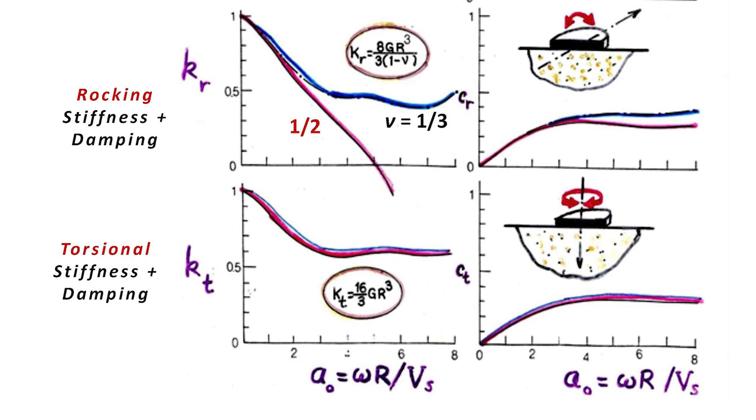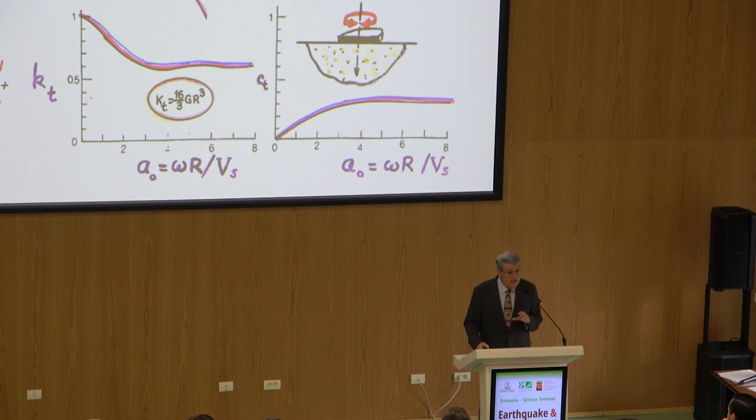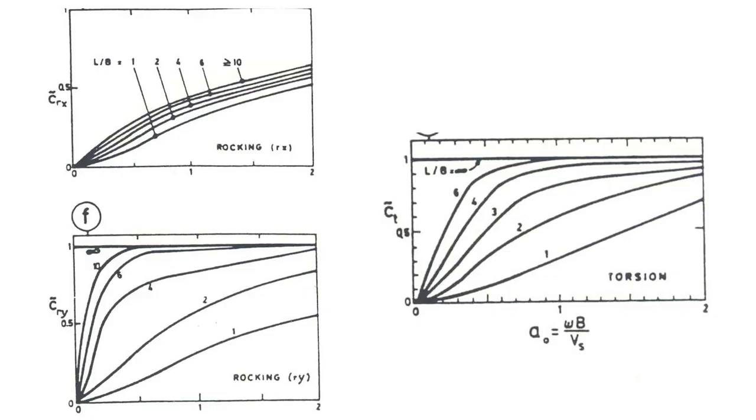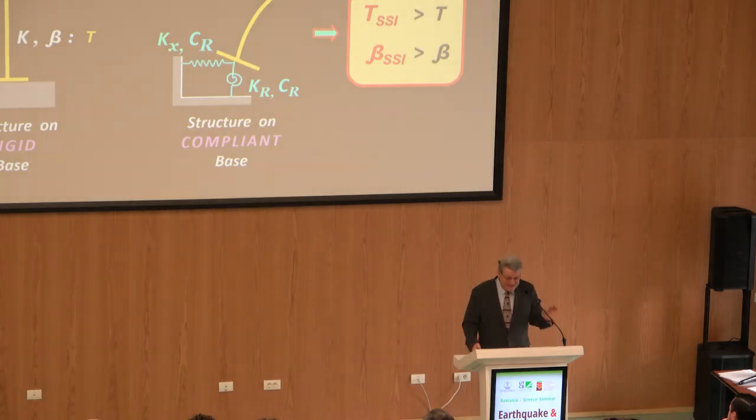Now, the rotational KR stiffness, or the circular, is very significantly affected by frequency in normalized form on the right axis. But the important thing for us is the rotational damping. It's much smaller overall, and it starts from zero. It's very small at low frequencies. And this is the range, if I may show here. No, it doesn't show very well. This one? No, that's all. You can see the small values of damping. This is very significant for our analysis. But anyway, there are, for all kinds of waves, you can see, as we present later, exactly how the Eurocode